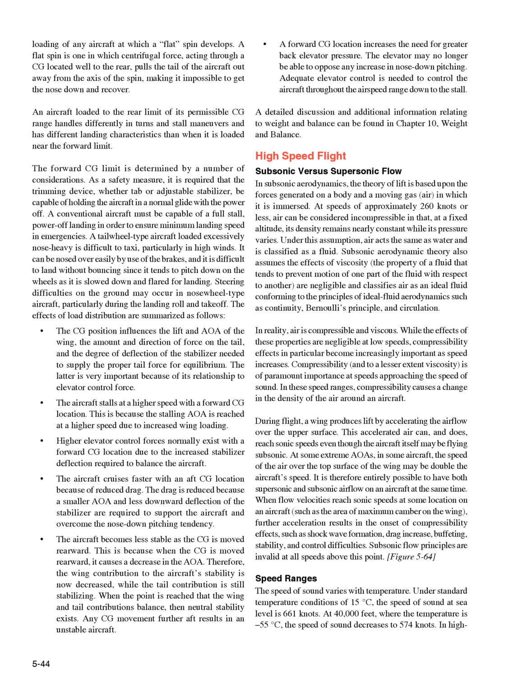Subsonic aerodynamic theory also assumes the effects of viscosity, the property of a fluid that tends to prevent motion of one part of the fluid with respect to another, are negligible, and classifies air as an ideal fluid conforming to the principles of ideal fluid aerodynamics such as continuity, Bernoulli's principle, and circulation. In reality, air is compressible and viscous. While the effects of these properties are negligible at low speeds, compressibility effects in particular become increasingly important as speed increases. Compressibility, and to a lesser extent viscosity, is of paramount importance at speeds approaching the speed of sound.